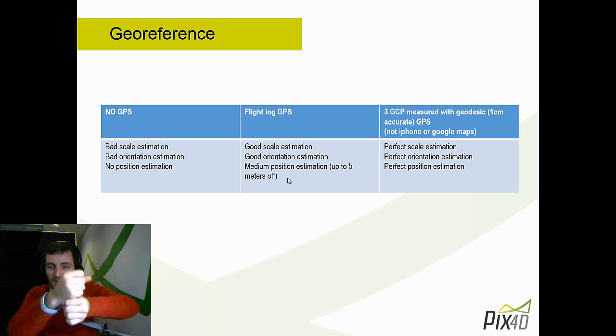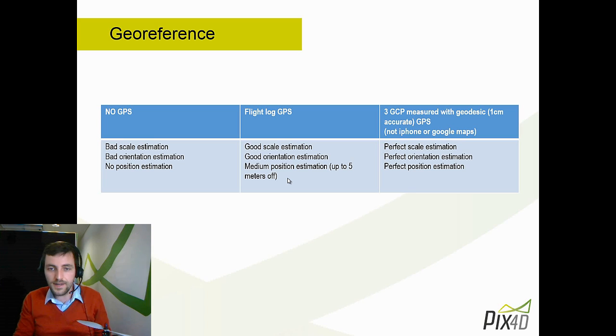You would write this down in a log file, and then do the flight and the processing. There's a way in Pix4D Mapper to import these ground control points and mark them in the images to get an absolute positioning of the project.